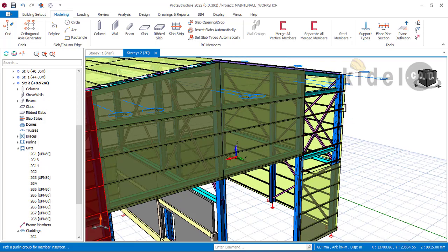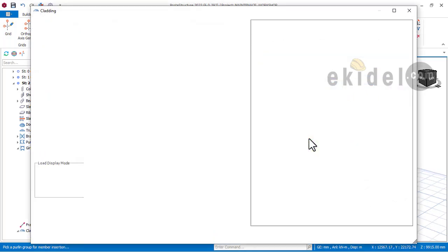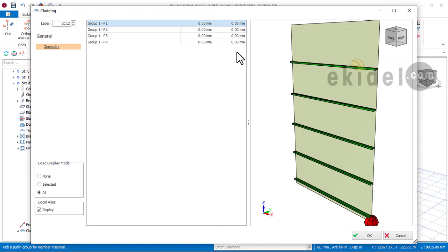Okay, so let me now create again for this other side here. Now click again and click on this place there. Knowing that I said that for cladding, when you're working with slope, you have to work anticlockwise and clockwise. The other one we did before was a clockwise one. Now this other side, I'll still make this place to be 0 and this to be 0. Now for P3, instead of having P3 to be 224, in this case I'll have to make P3 to be minus 200, and then P4 will now become 224. So that's how it works.